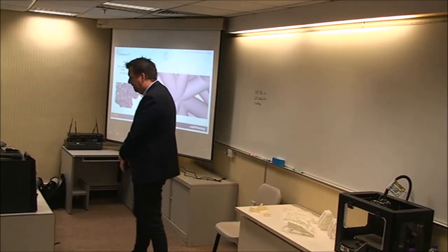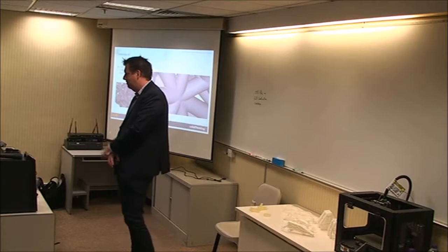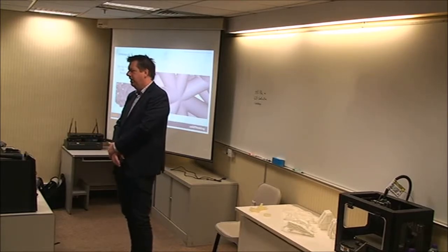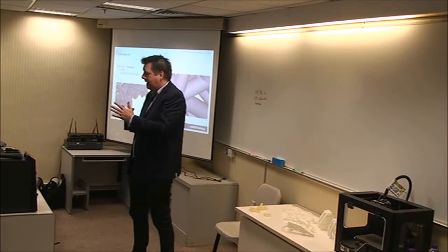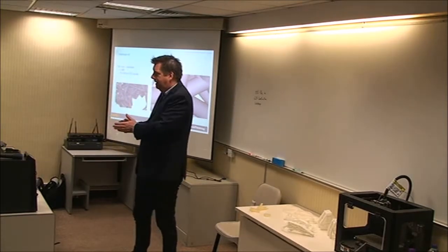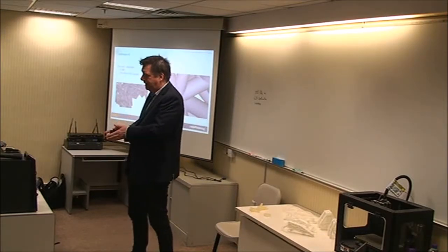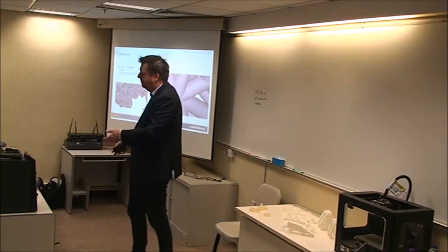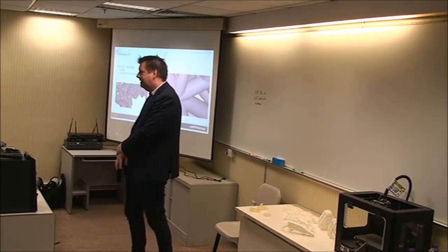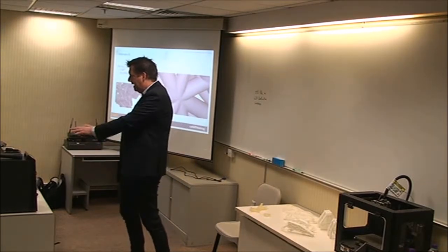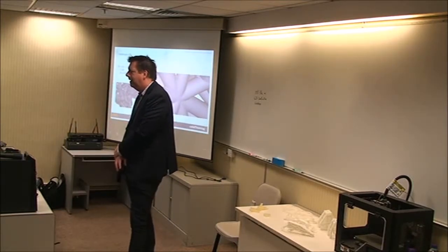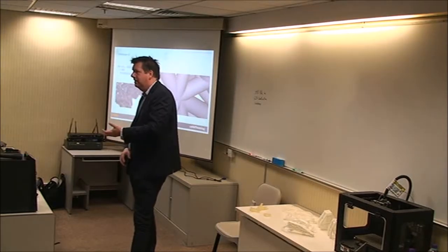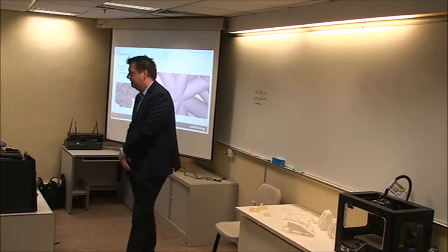The other thing I've been really struggling with, I've got a pretty high performance laptop. The file size of these lattice structures is huge. So you generate a lattice, you want to take it to your 3D printer. The standard method is an STL file. I created one this morning that was 4 gigabytes, the STL file. Fans go on, the laptop starts lifting off the desk, it gets so hot. So even just handling them starts to become a bit of a challenge. That's doable, but just beware.